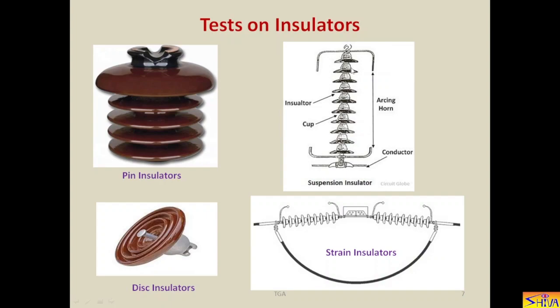So these are individual units. They are insulators, and these are called caps, and this is the lightning arrester, which is used to protect this string from lightning or voltage. Conductor is at the bottom. This part is connected to the tower. So if there is lightning or voltage, the spark over or flashover will take place in the air between this power conductor and the tower.